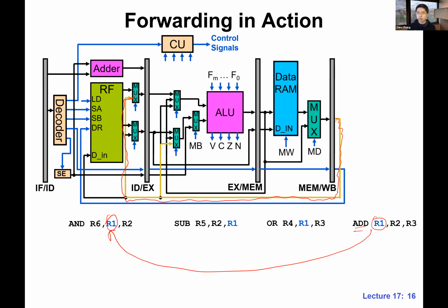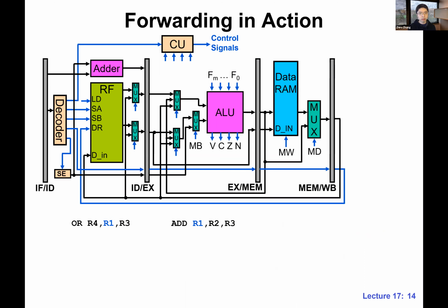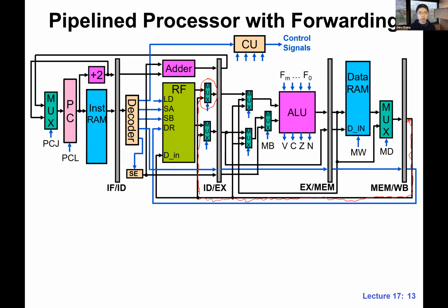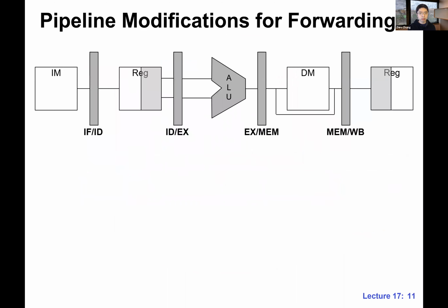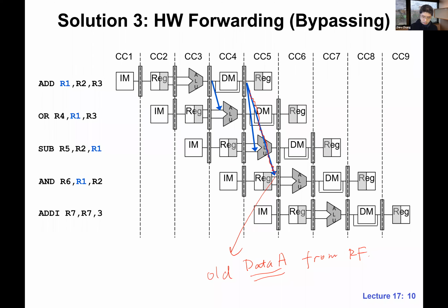Okay. And also, on my thing, I saw "we cannot forward twice in the same cycle." We can forward twice in the same cycle, but we cannot forward across different cycles, right? So if you come back to this diagram, we are actually doing 2. We are really enabling 2 forwarding passes in the same cycle, CC5.